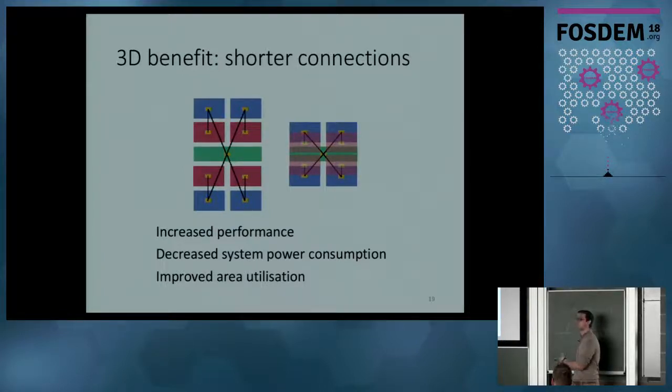They also improve the area utilization simply by reducing the routing congestion and limiting the use of buffers, since the nets are shorter. So a lot of benefits just by making all the wires shorter. Now, for the rest of the presentation, we'll see how we can transform a 2D RC into a 3D RC using existing 2D flows, and what blocks we need to add to make that transformation.